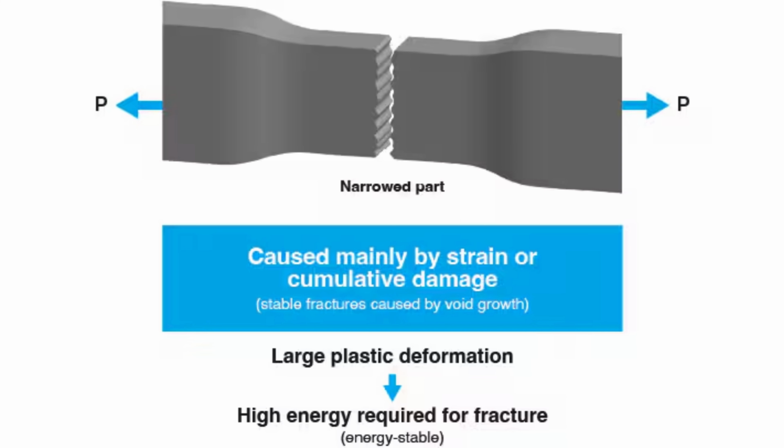Fracturing of plastic molded parts occurs when the molded part can't endure an impact load beyond the plastic material's limit strength. As such, fractures occur in various ways, influenced by the applied plastic materials, design of molded parts, operating conditions, external circumstances, and so on.